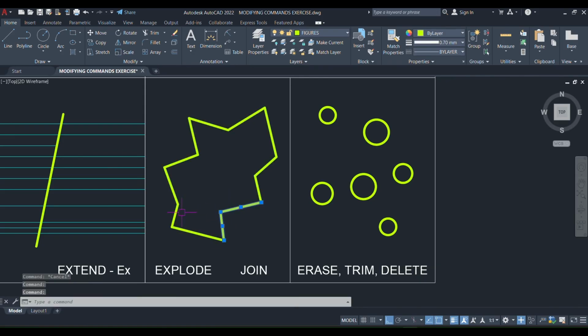Okay, so you'll notice that from a singular object, like from a singular polyline, it's now segmented. Okay, now let me do that again. So, okay, if you click it once, you'll notice that again, it's a single polyline. Now you want to explode it because you want to edit it, maybe. Type in explode in your command line. So now the lines are separated.